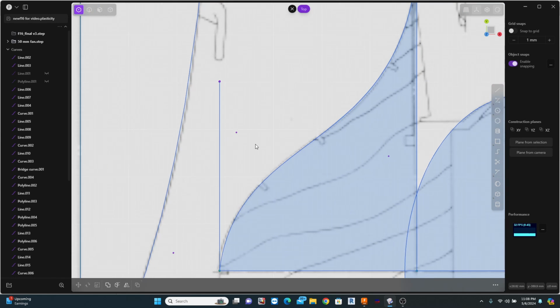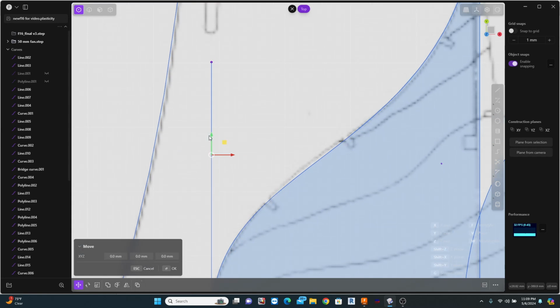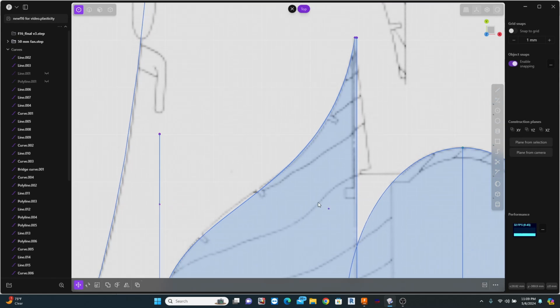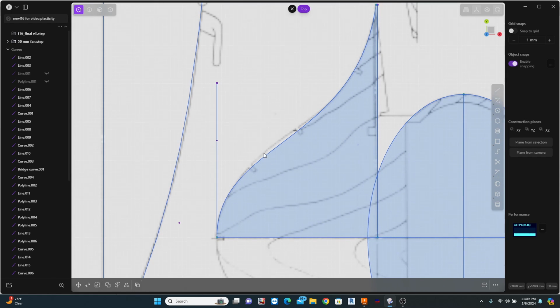Okay, this is important, or at least I thought so. You see me drawing a line here, and I'm using one of my control points, and I'm snapping it directly to that line. Since that is the same line or plane as the original one, that actually will create a tangent curve from that point, so you shouldn't see a seam when this gets mirrored.